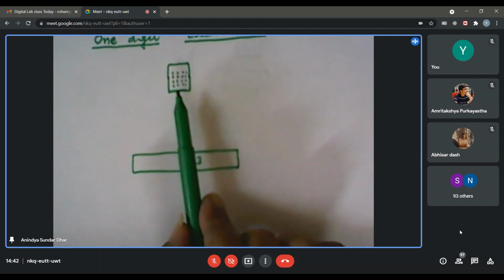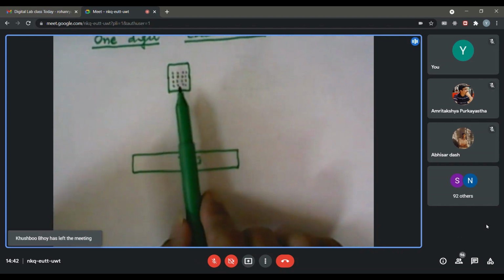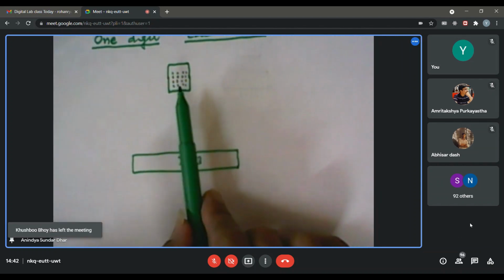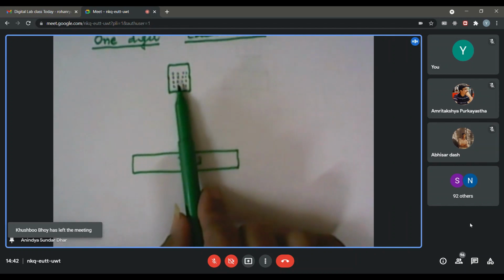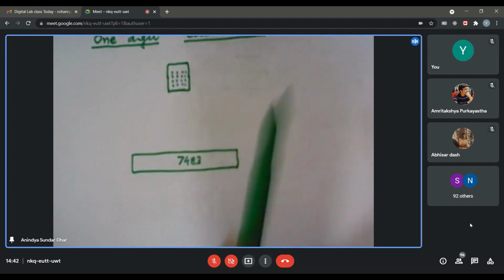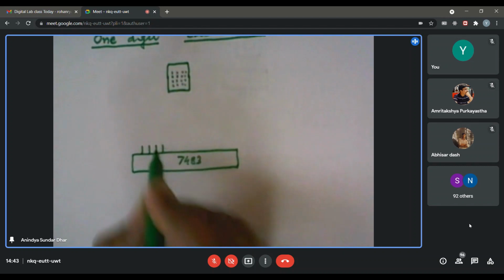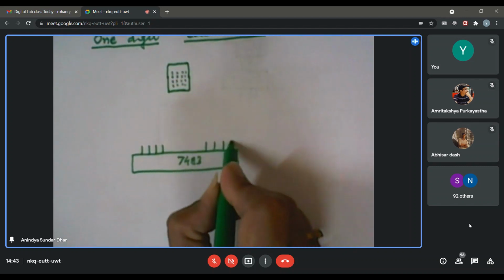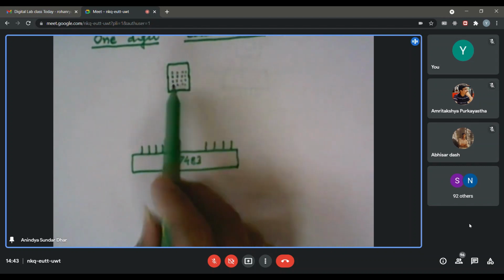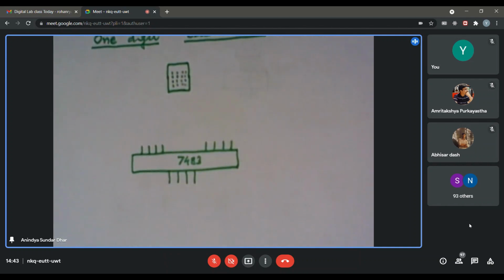As we do in a calculator, from the same keypad we give all the operators or operands. I think right now I need not give the operator, it is only addition. I will give 2 subsequent digits. So I will press 2 keys successively, one after another, and I would expect the 7483 to generate the result. For example, if I press successively 2 keys like 2 and 3, I'm expecting a result 5 over here. So can you tell me how you would design it, or whether you think of any problem?